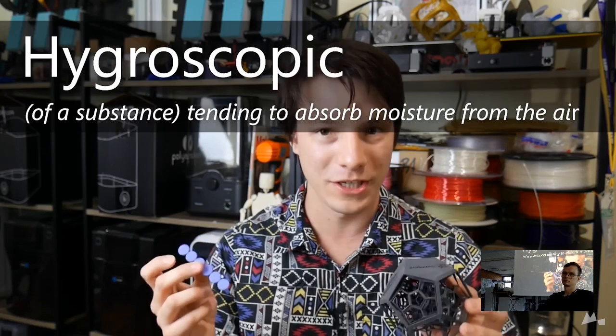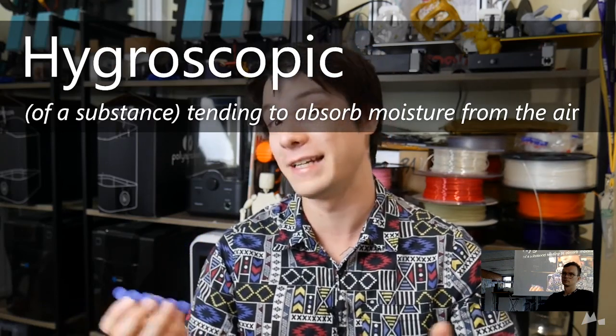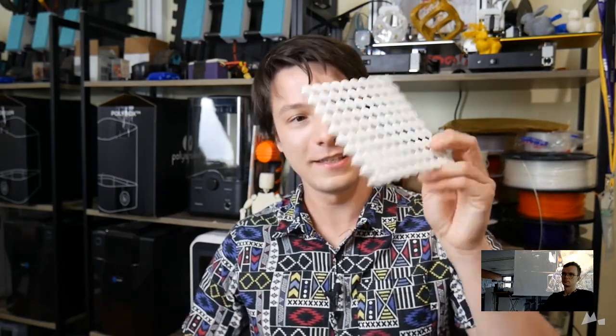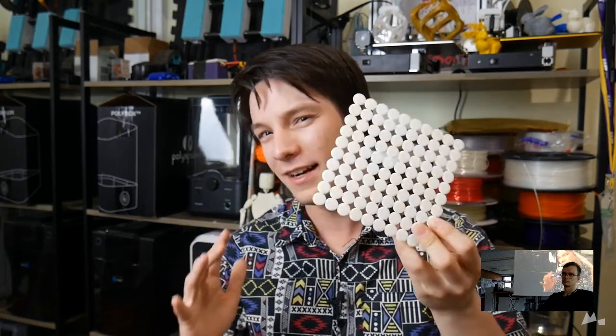It absorbs moisture. It absorbs moisture really quickly. If you've been FDM printing with nylon, you know it absorbs moisture almost instantly. And because you can dye it, it's absorbing moisture, not only because it's nylon, but also because it's sintered. It's not completely melted. The nylon actually can have stuff wick into it. And to show what kind of effect this can have, this is some nylon that's been rarely touched.